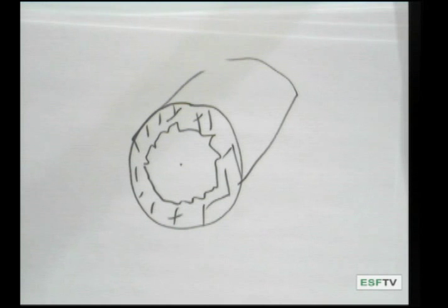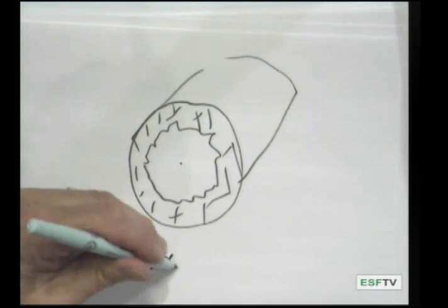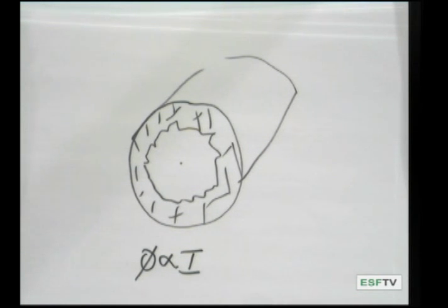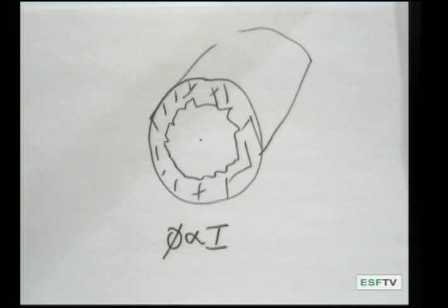Now, where this comes into flexural stiffness is that the flexural stiffness of an object is also directly proportional to the second moment of area, which we symbolize as I. So now we have three things that feed into the flexural stiffness of an object: the length of the material, the Young's modulus of elasticity, and the second moment of area. And what we can do is calculate a formula.